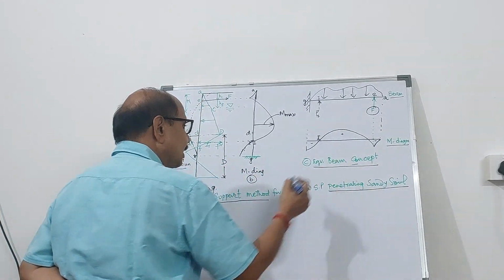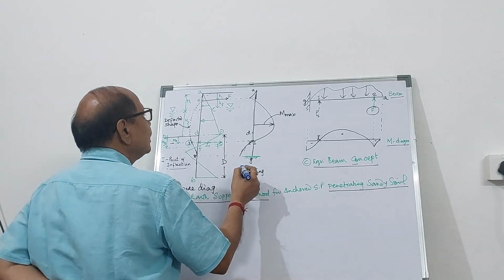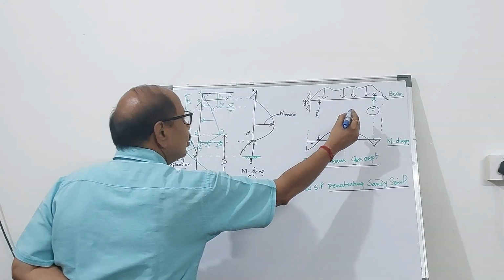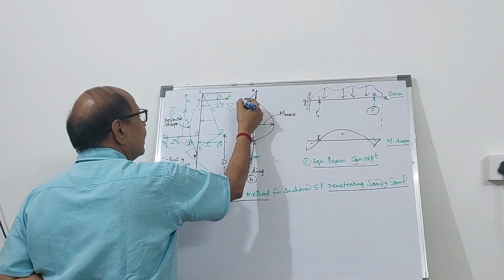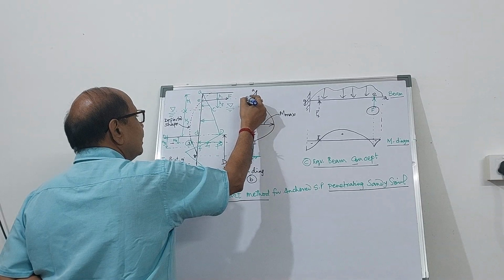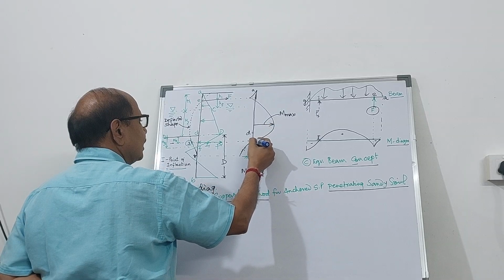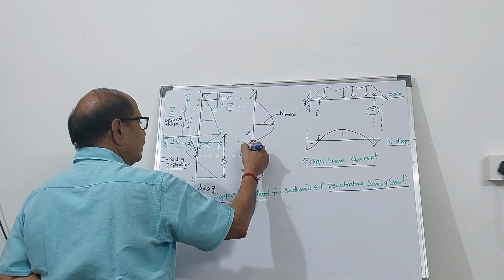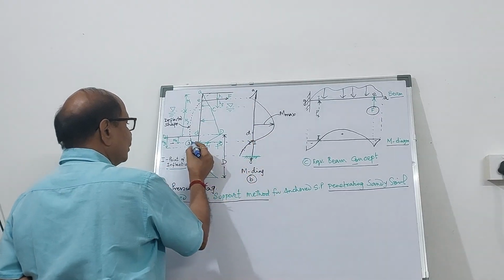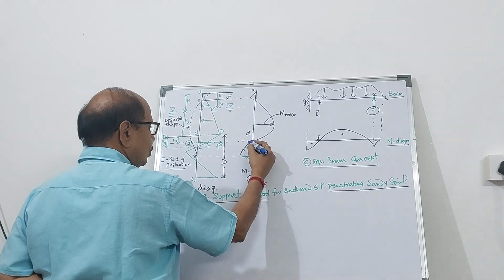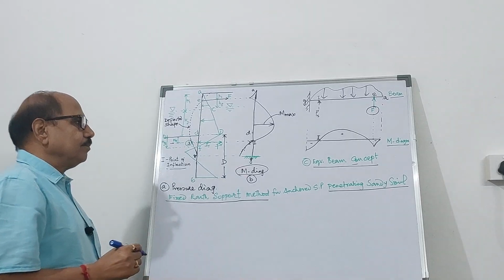So we have shown this concept of the equivalent beam, and the pressure distribution is well known to you. Therefore, as you have seen, between A and E it is going to be a hogging bending moment. And then from here, it becomes a sagging bending moment or a positive bending moment. And then at the point of inflection, I, it is going to change like this. So this becomes the bending moment diagram.